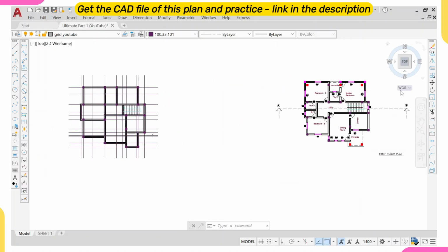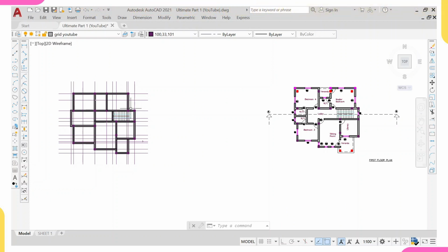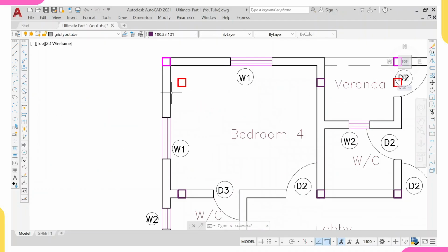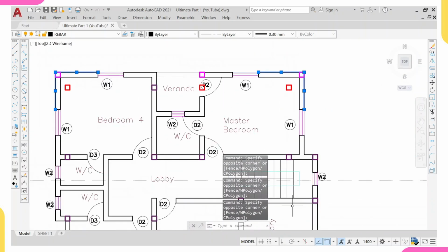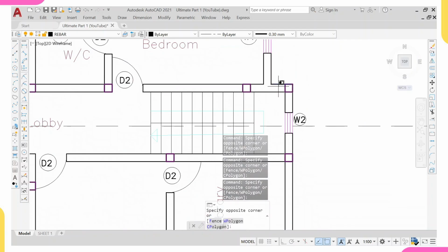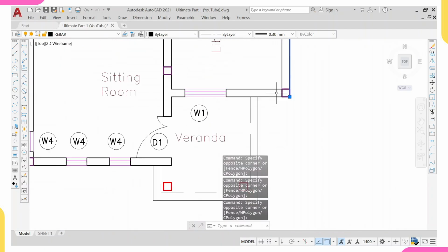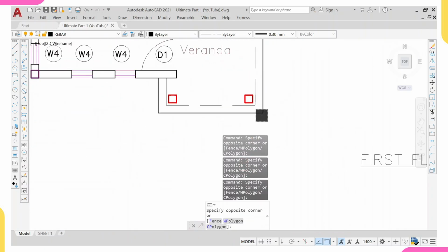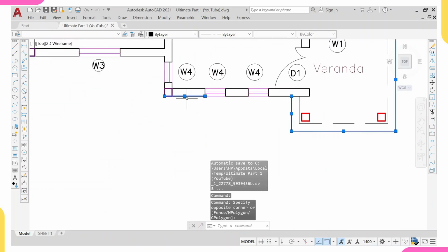So the next thing I would like to do is, for example, we have seen that we'll be having cantilevers on our story one. But we don't really know where those cantilevers are here. So for easy modeling in ProtaStructure, I will highlight the boundaries of this story one. Don't worry, once I'm through, you'll understand what I'm doing. I just want to highlight the whole boundary of this story one, just to know the places where I'll be having cantilevers.